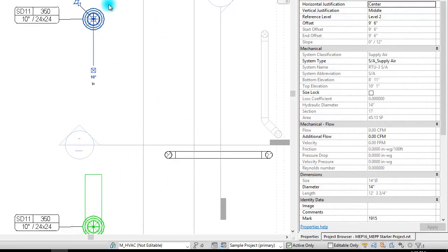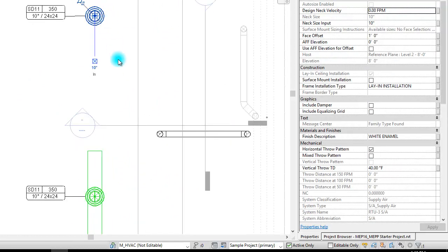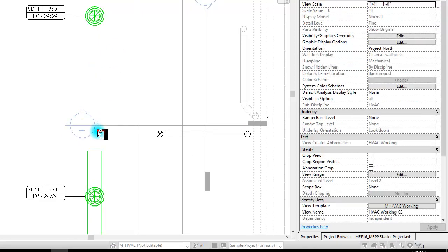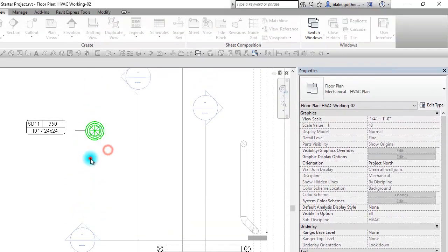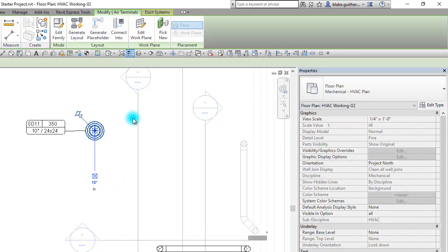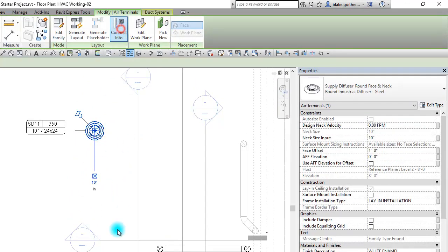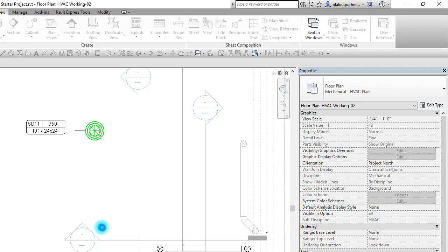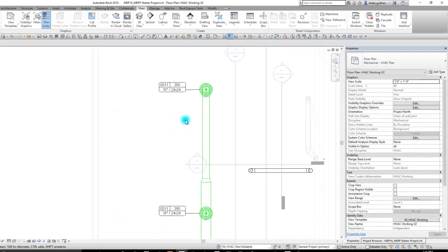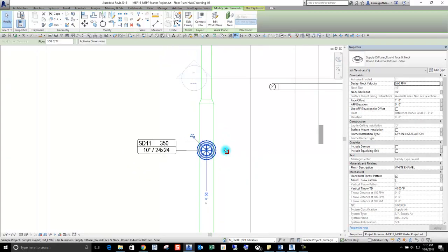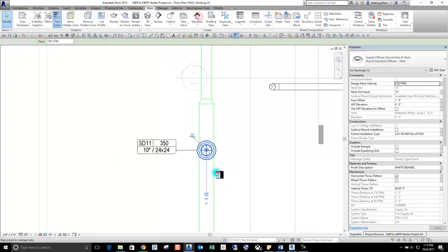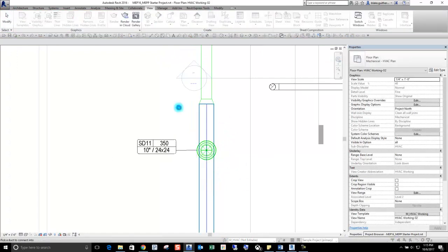A lot of times I use connect into, so selecting diffusers, you can hit 2.5. Sorry, that's my keyboard shortcut. You can select a diffuser and hit connect into here, and then you can choose any nearby duct. It's really nice because it'll put all the bends and offsets in for you and make the connection for you, saving time. Even this diffuser that's right underneath, we can use connect into, and you can choose your duct.